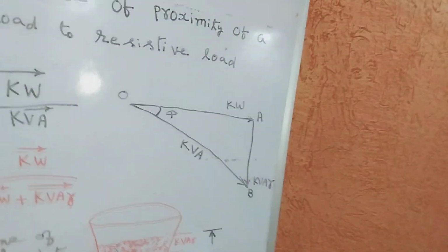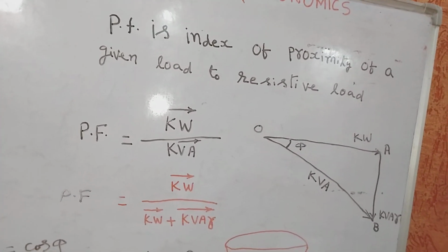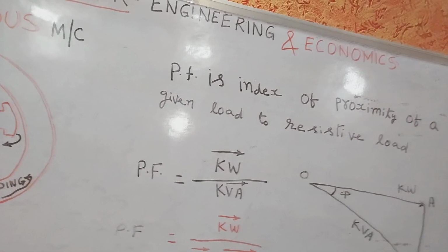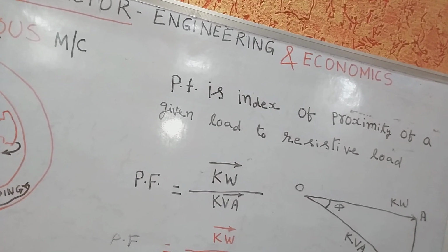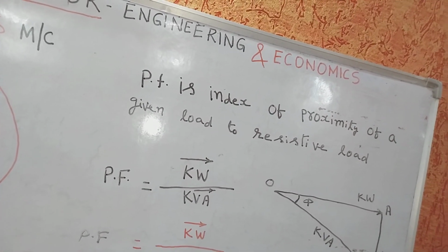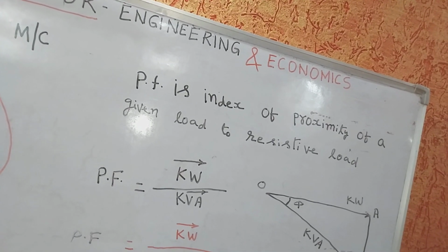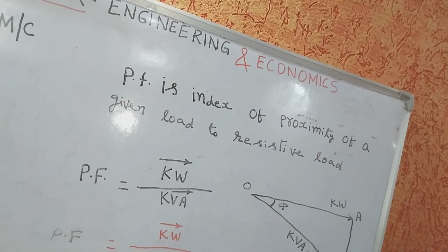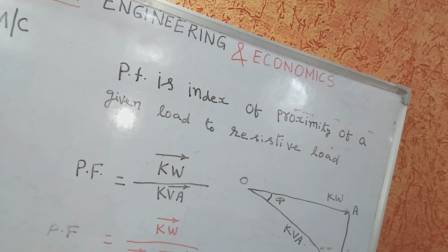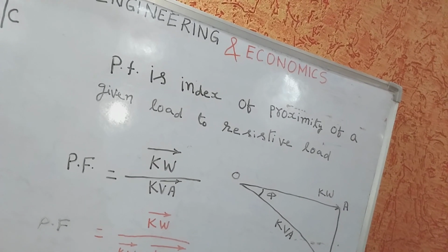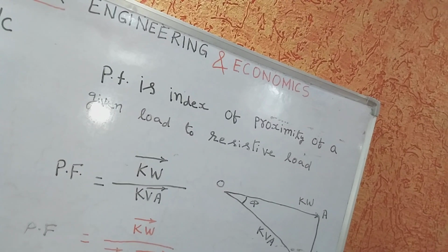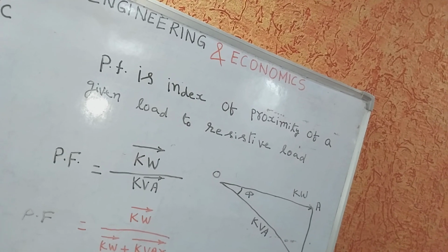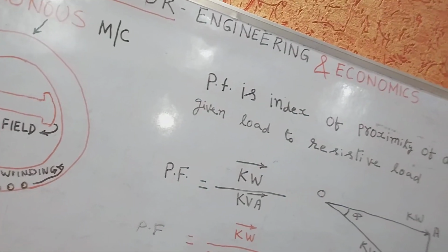Because magnetizing current must be supplied in inductive loads such as transformers and induction motors, the ability of an overexcited synchronous motor to supply lagging current is a highly desirable feature which may have considerable economic importance. In effect, an overexcited synchronous motor acts as a generator of lagging reactive kVA and thereby relieves the power source of the necessity for supplying this component. They thus may perform the same function as a local capacitor installation.